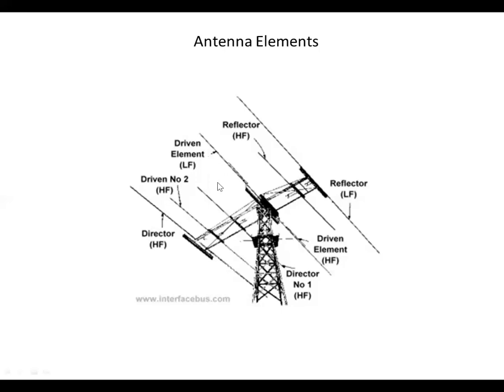So both of these antennas would have more gain in one direction than a single element dipole. Now the cost, what you give up for that, is you get more gain going in this direction, but the gain perpendicular to that is much lower. So you're not getting as much power out the side of the antenna as you would with a single dipole, but you are concentrating the power coming out of the antenna into the direction you want it to go. And that's why a lot of, yeah, go ahead.